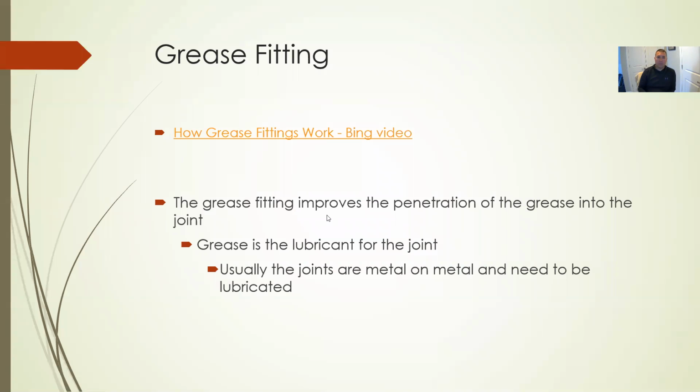So that kind of helps you understand a little bit, right? Like I said in the beginning, I thought it was a little longer than that, but it's okay. You can replace that fitting fairly easily. But those things do malfunction. They do allow particles in there. Cleaning and being able to visually inspect those things is the best way to catch that. Obviously, when you're greasing it, that's one thing too, but if that thing is still clogged, with a bunch of debris and all kinds of things on it, it's hard to see as well, okay?